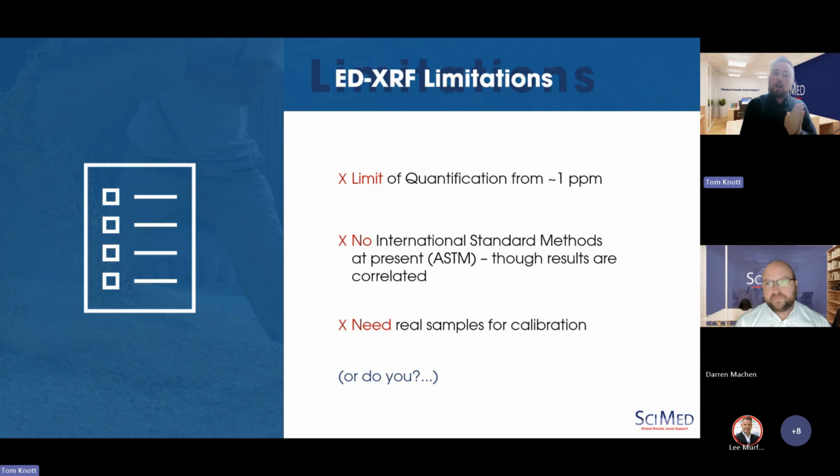And again, unlike methods like ICP, though I believe this is slowly but surely starting to change, at present, as of recording this, there are no international standard methods that describe the approach for XRF specifically as a method, as there are for techniques such as ICP. Now, the results from XRF are being shown as highly correlated and aligned with those techniques. But for those needing to comply with standard test methods, it's important for me to highlight that those don't currently